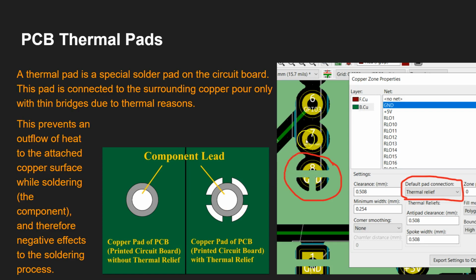These thermal pads are usually positioned between a hot component and a heat sink to help conduct the heat from the component into the sink. Thermal pads can be much easier to work with compared to thermal paste, which is a little bit messier. We're going to learn about that in the next slide.